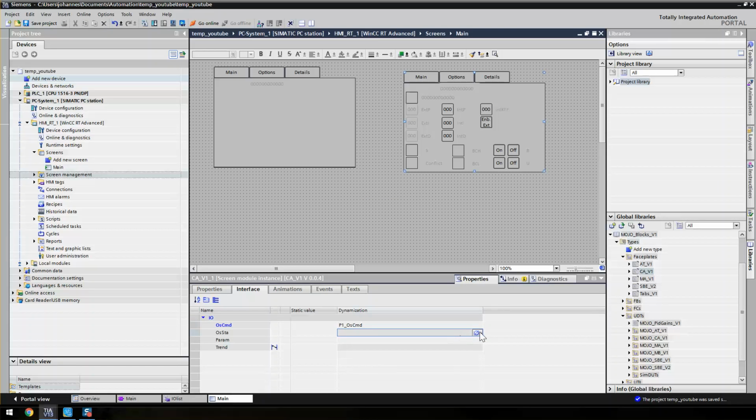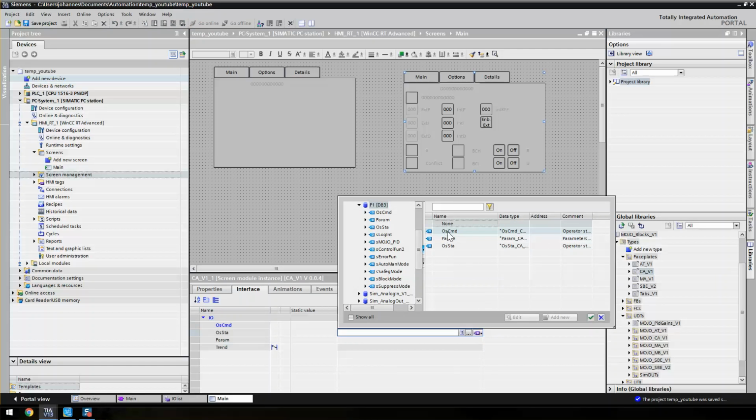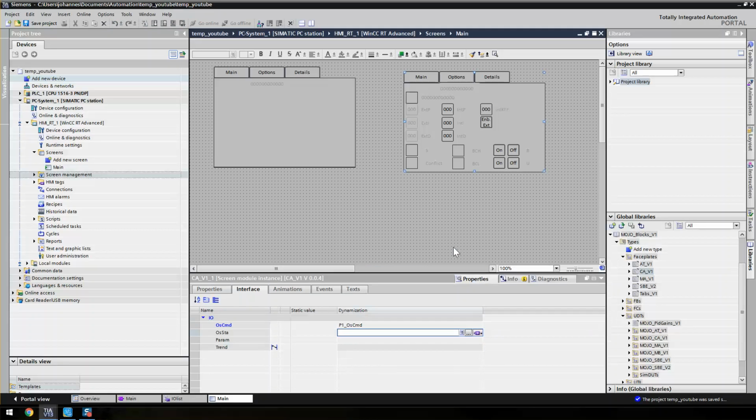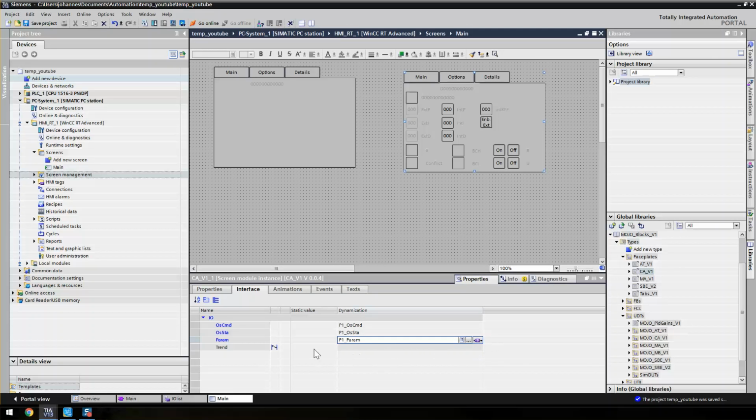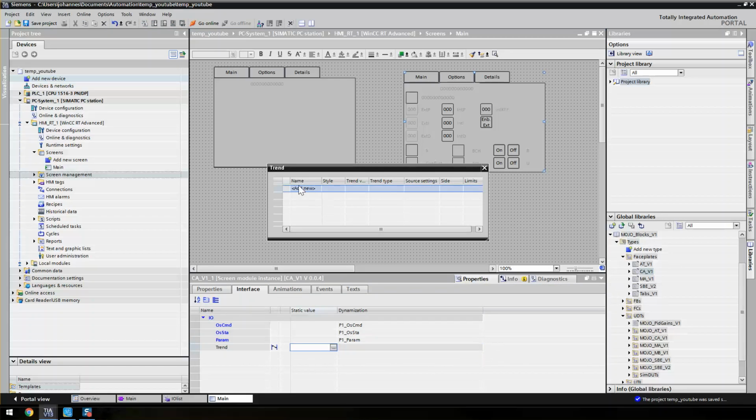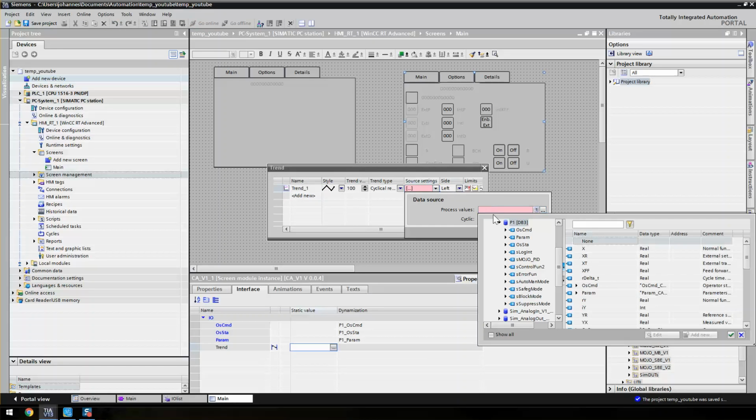We could expect that with a decent framework and a decent library, 80% of all our PLC coding would be just parameterizing, setting stuff up, and leaving just 20% of custom code, project specific code, which would make us way faster. Just better at doing process control. There's no use in inventing the wheel here.